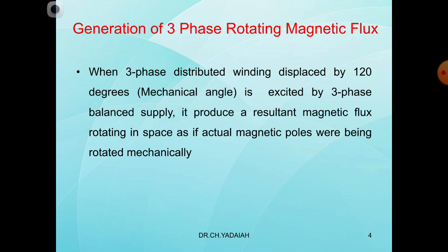This is one method we have seen. And another method: if it is not possible to provide the mechanical motor initially, because it is also costly, then after running at synchronous speed we have to decouple this motor. Otherwise, what will happen? It is connected to the same shaft, so it acts as a load on our synchronous motor, hence this is a problem.